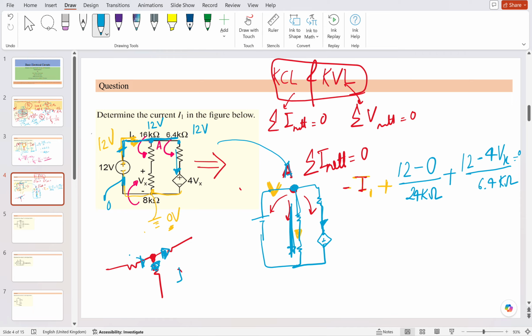The basic definition is that whatever current is incoming will be the current outgoing. So summation of I out is equal to 0. Whatever current is going out of the node I consider as positive, and if it is coming into the node, I consider it as negative. So the whole summation becomes 0.